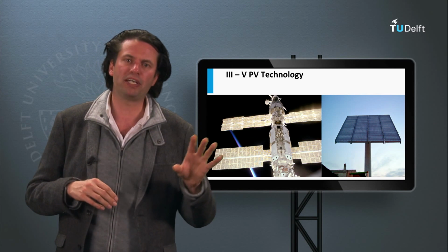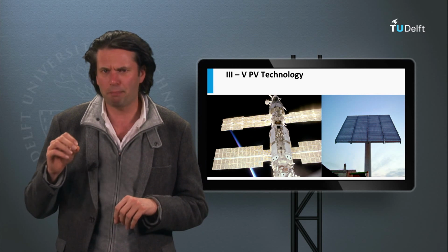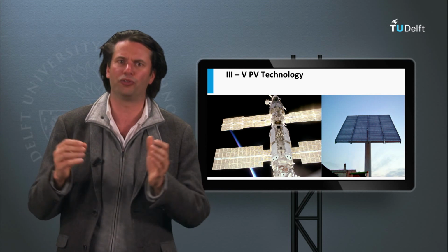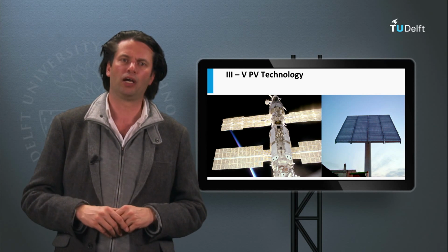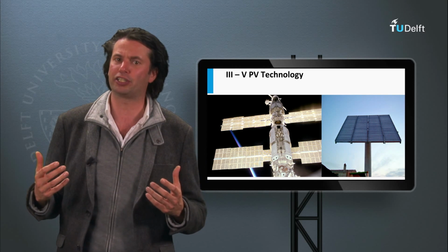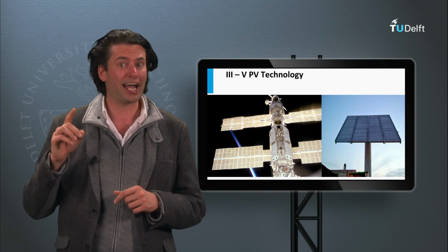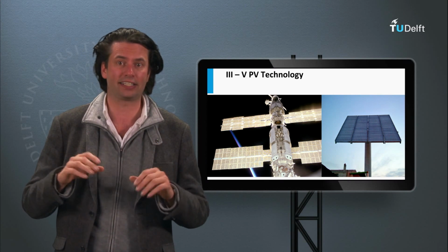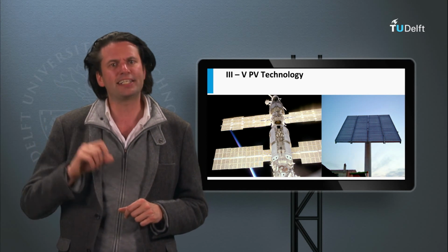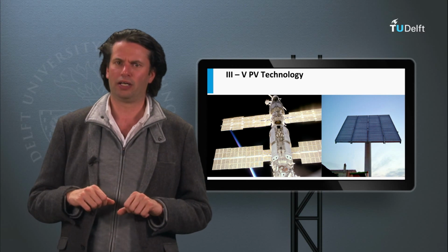The dollar per watt peak of a small, expensive III-V multi-junction device can be improved by concentrating the irradiance of a large area on the small solar cell device. An advantage of concentrating sunlight is that the open circuit voltage is increased with irradiance as well, as long as Auger recombination of light-excited charge carriers does not become dominant. Important is that the small solar cell devices have to be actively cooled.